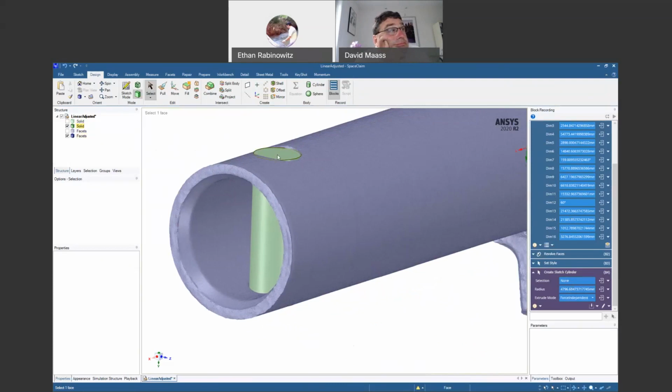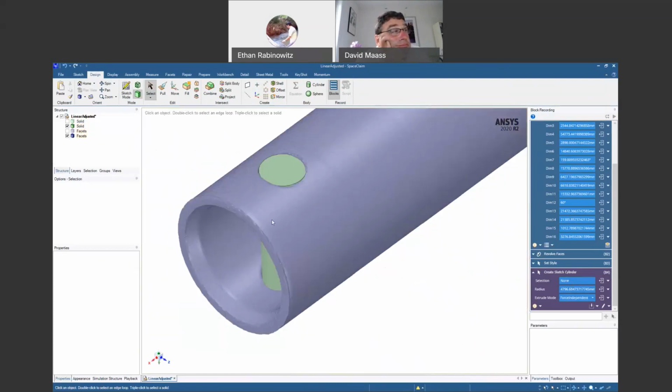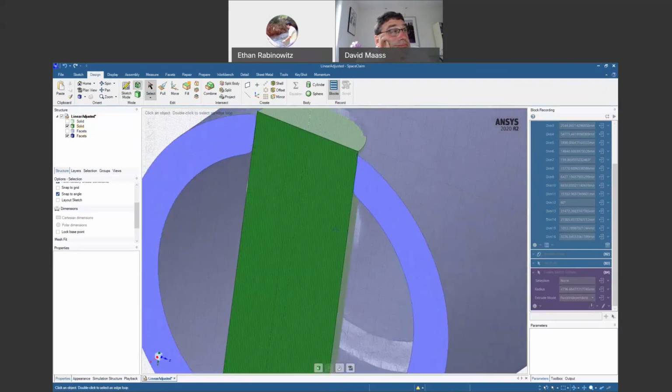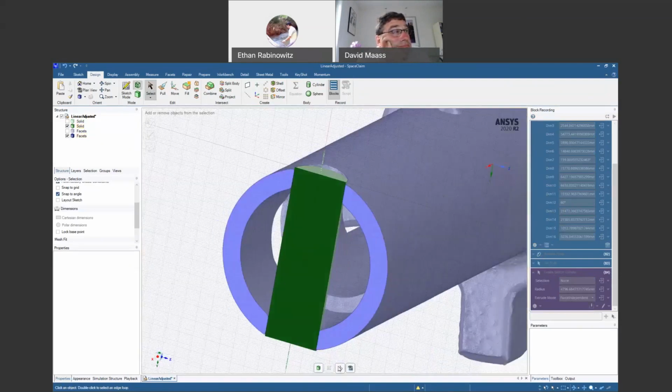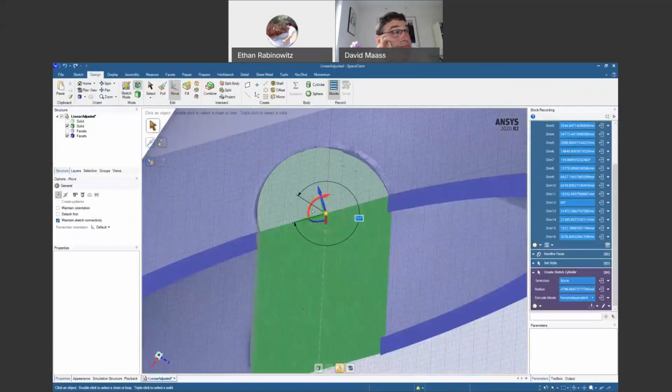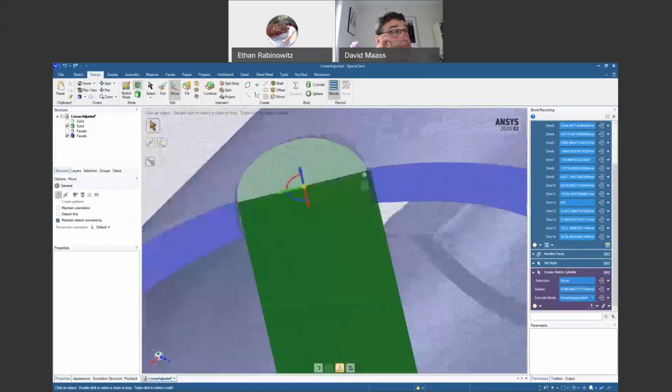So we made the pin. Let's do this. If I hover over the pin and then scroll my wheel to this little axis, I could go into a cross section. So if I just want to see what the fit looks like, I can take our cross section here and rotate it around. So those were just those areas that didn't look like they were scanned too well.